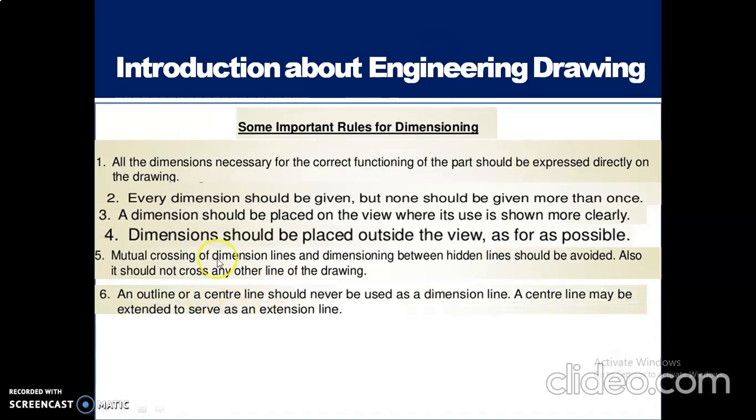Next, the sixth dimension rule: an outline or center line should never be used as a dimension line.